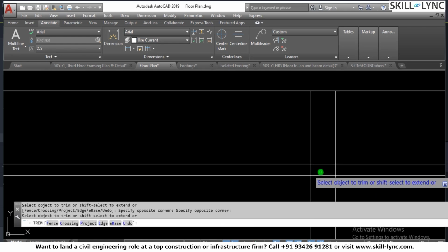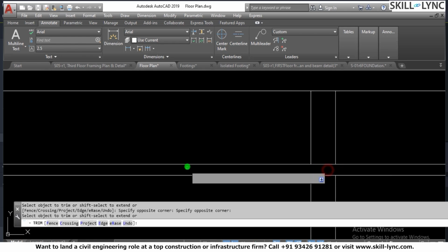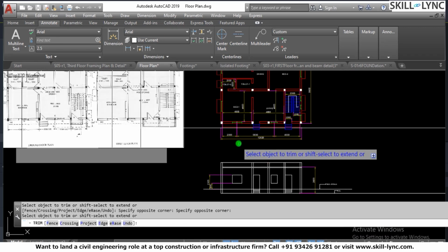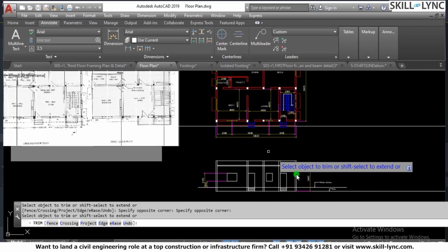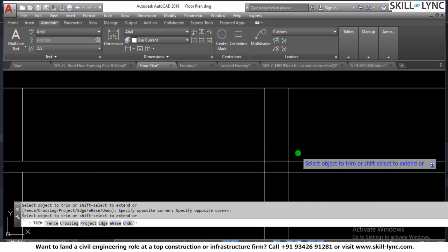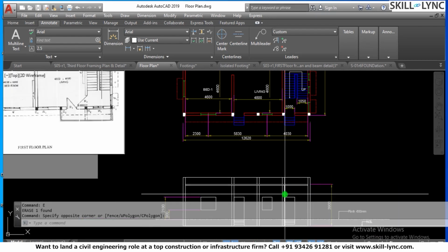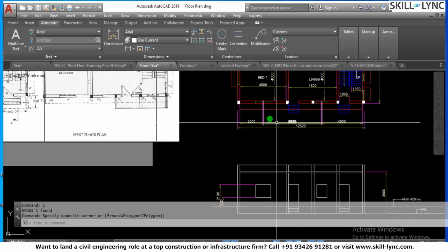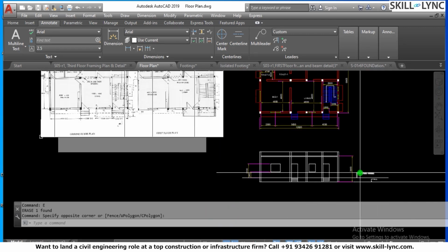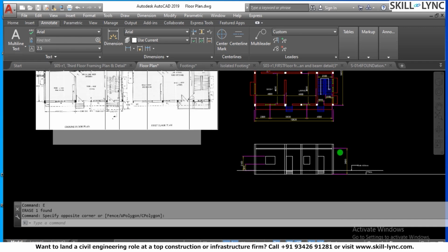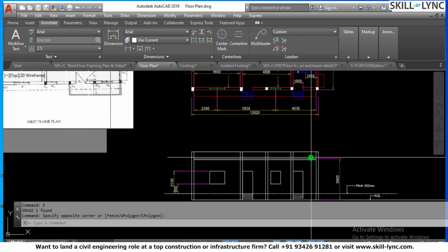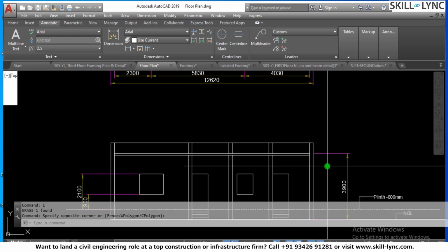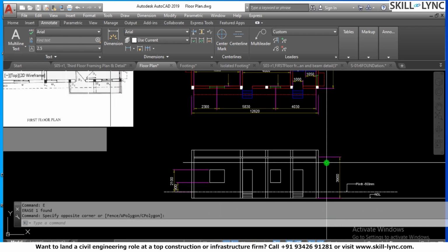Now this sunshade is protruding outside the column, so the lines will be major lines. So we have created the sunshade. Now you can see the sunshade is created. This is a sunshade. Then we can also see that there is a projection over here. The sunshade over here, the chajja, is coming at the top at the height of, let's say, we can have the height.